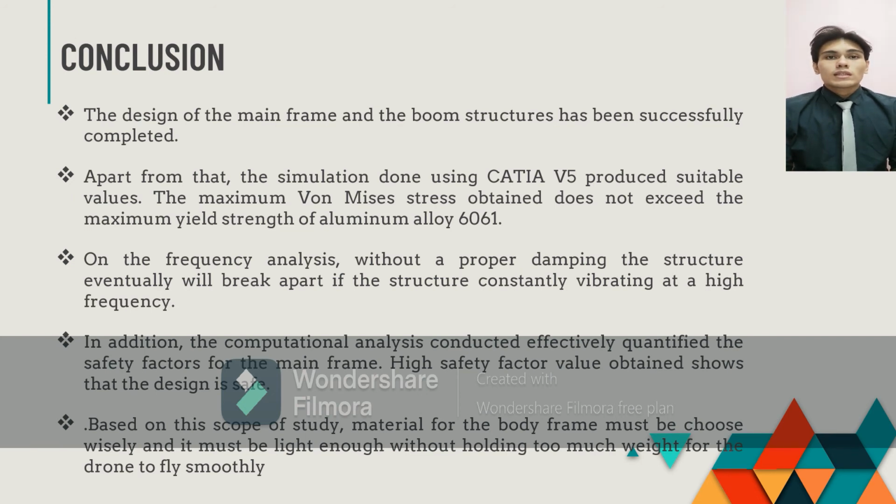On the frequency analysis, without proper damping, the structure will eventually break apart if it constantly vibrates at a high frequency. In addition, the computational analysis conducted effectively quantified the safety factors of the mainframe. High safety factor value obtained shows that the design is safe.